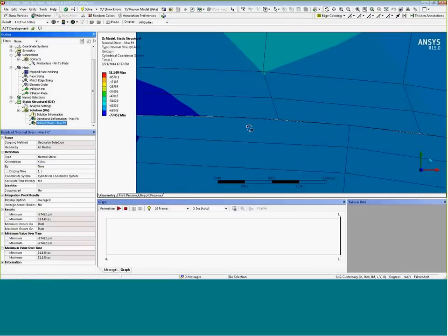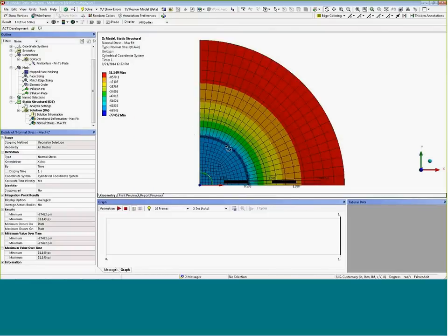And all that means is that across this one face of this element, there's a couple points on this surface that are looking to not penetrate the target segment on these other element faces right there. So that's the detection. It's still essentially like a point-to-surface type of contact, which leads to some of this irregularity that we see around the results in the circumference.